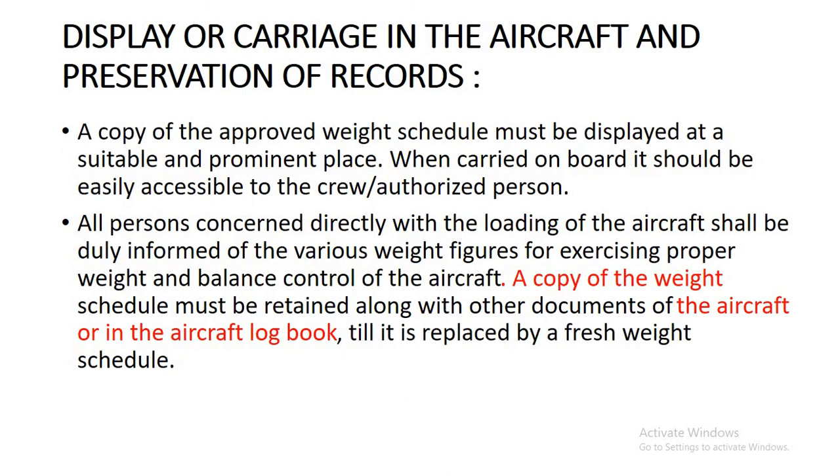Then after weighing, where will you keep a copy of this? A copy of the approved weight schedule must be displayed at a suitable and prominent place, and if it is carried on board, it should be easily accessible to the crew as well as the authorized persons.